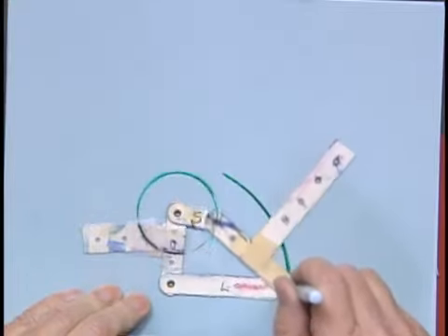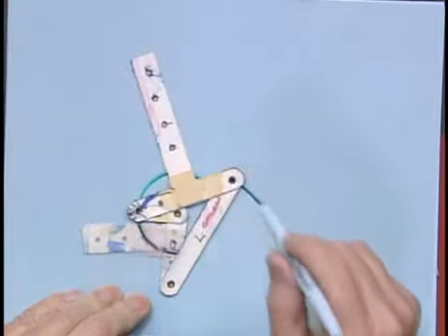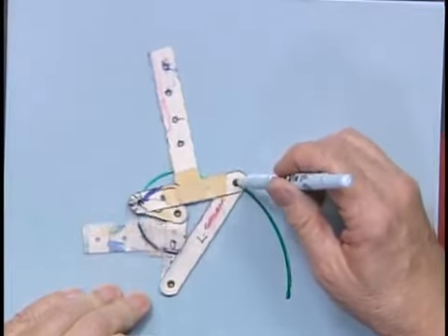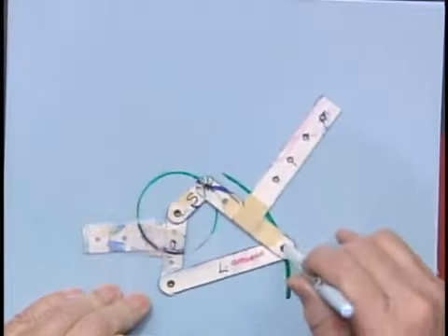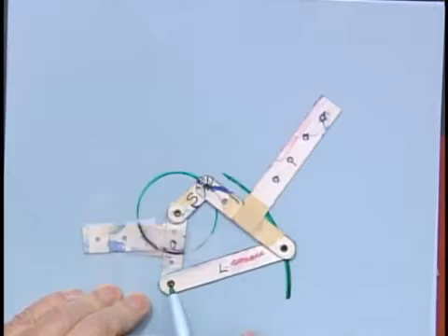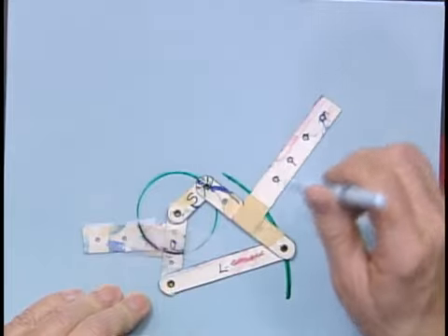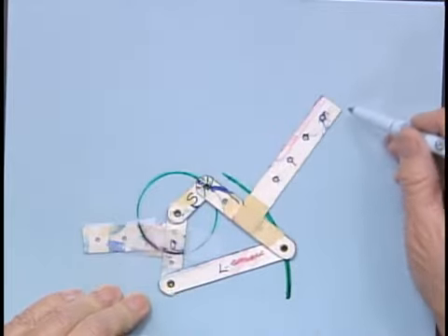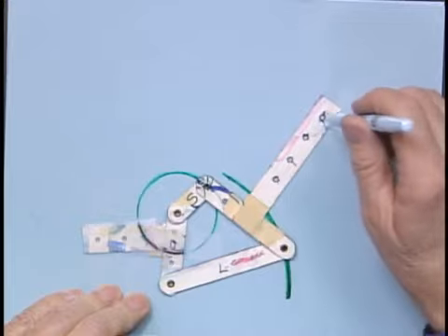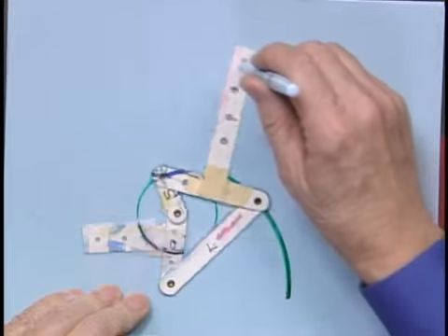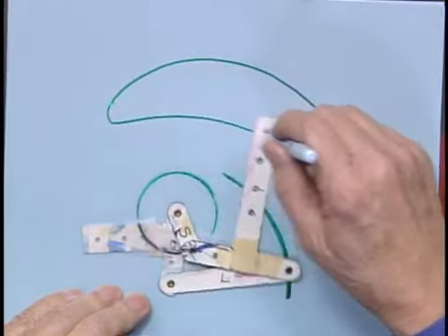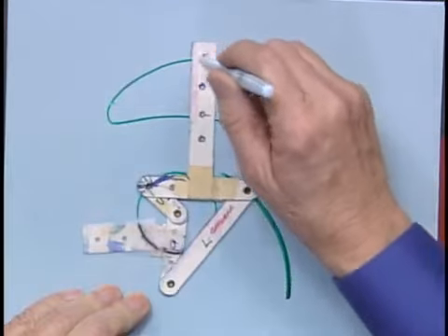that's in fact a coupler curve because it belongs to link 3, but it's another one of those degenerate versions because it's gone down to 2nd degree by reason of the fact that it's also constrained to pivot about instance center 1, 4 down here in pure rotation. But now, I've extended the coupler up here with a piece of cardboard and punched some holes in it. So if I drive it from there, I get something of a kidney bean shape there.